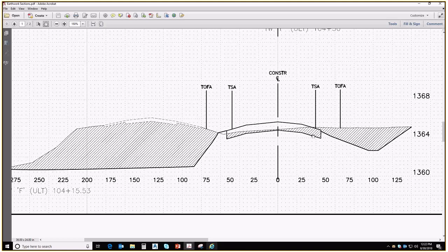All of these checks should be done by someone other than the project engineer or designer or EIT, whoever generated the earthwork. Someone else should be doing those checks. So check your subtraction from finished grade to subgrade to make sure it matches your final typical sections and accurately projects the width and the depth of those sections.